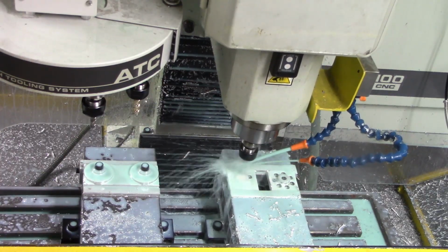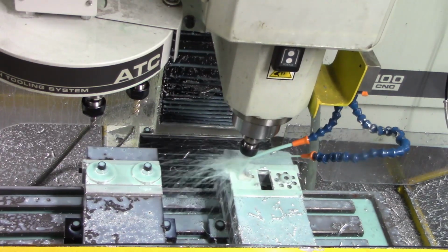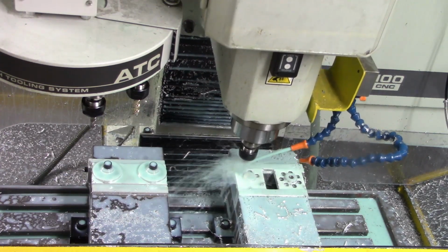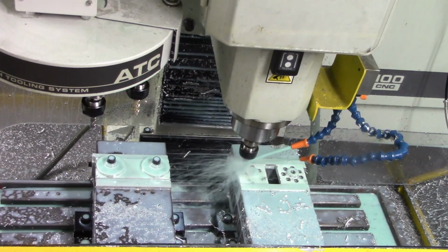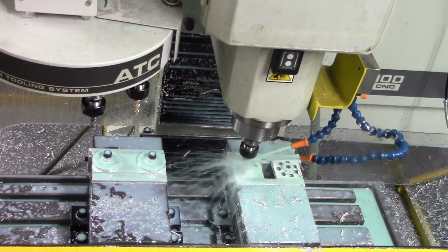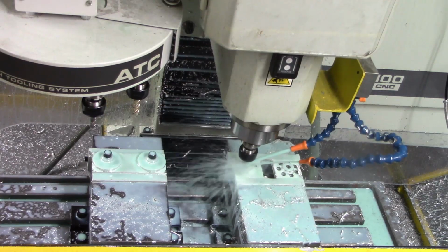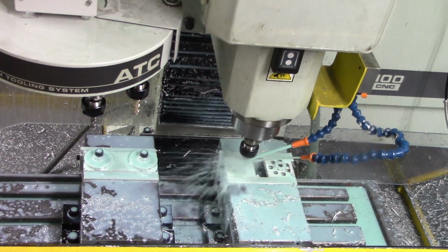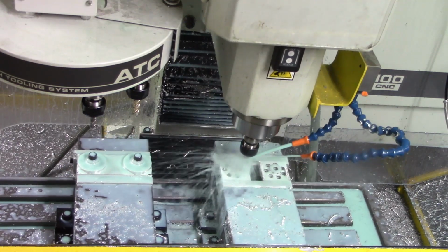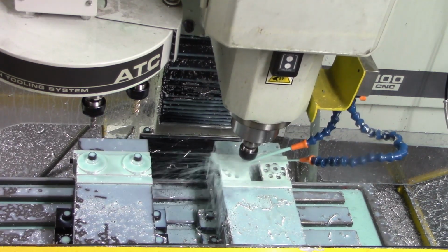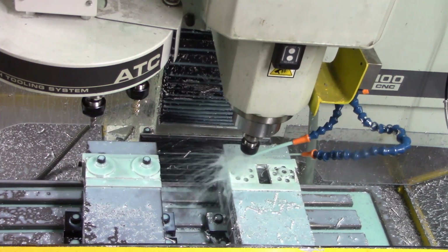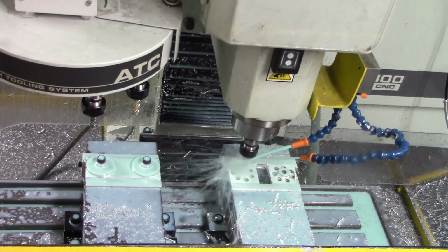That goes on the main axle, and the concentricity of that hole and the outside O-ring groove kind of determines how the glass piece is going to rotate. So I take the extra step, take the extra few seconds of drilling a 64th undersize and then reaming the hole to try to get a nice, accurate 3/8 hole.